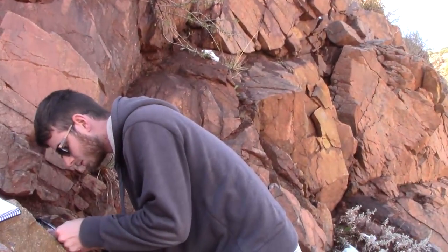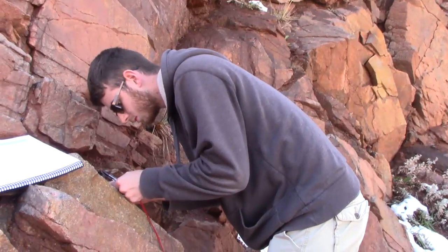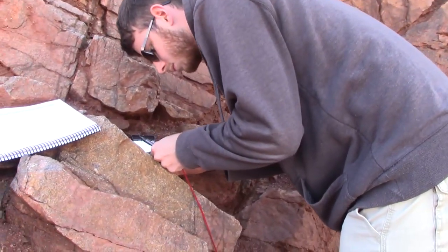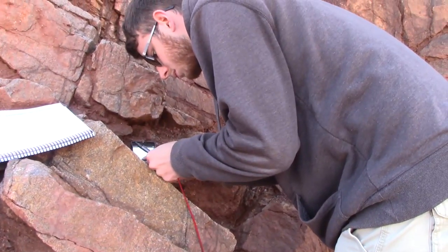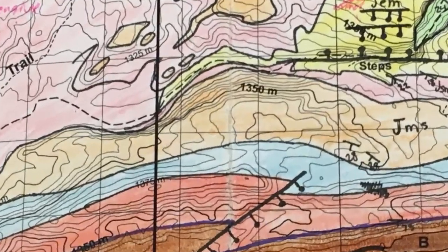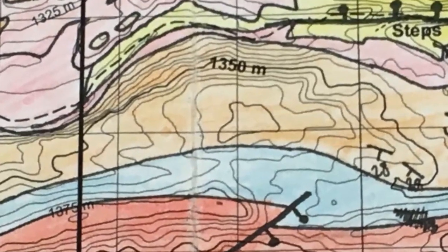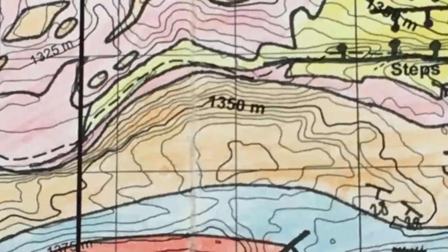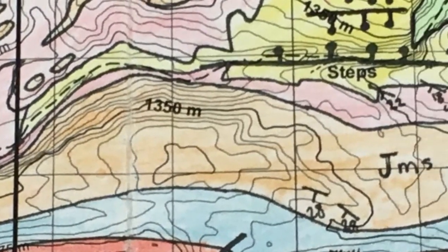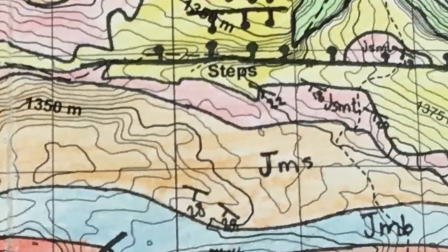Joints are also planar features that can be measured, and we can't keep using the same symbol on maps for all these structural varieties. We saw in the last episode that the strike and dip of a rock layer is represented with this T-bar, with a longer line in the direction of strike and the short crossbar pointing in the direction of dip, with the degree of dip at its endpoint. And before moving on, we point out that we use relatively thin black lines to draw out the contacts between rock units, and we can even put a dip symbol and value on such contacts, if known.